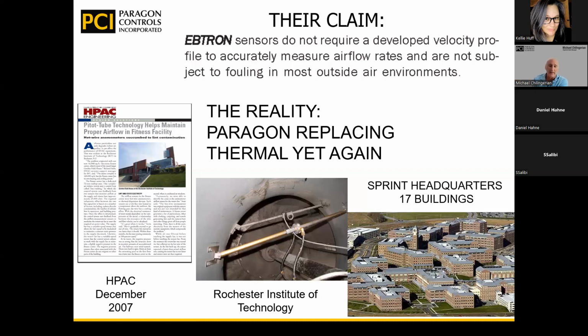Well, at a certain point they brought the return air to 100%, even though it didn't need to be, and they were blowing return air out the outside air dampers. The outside air dampers were seeing 70 degrees during the winter and saying, we need to bring on the compressors. Well, the compressors were short cycling, and they blew the compressors because the short cycling caused the oil to get hung up in the system. So at a certain point they said, we're done with this. We came in, and it's been running for years at Rochester Institute of Technology.